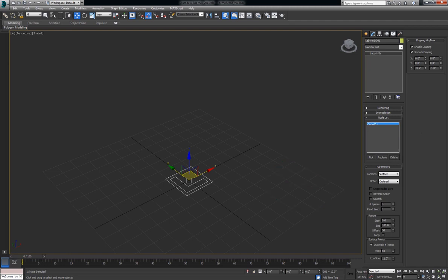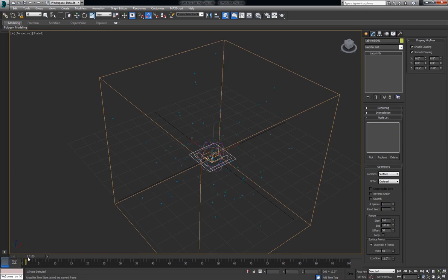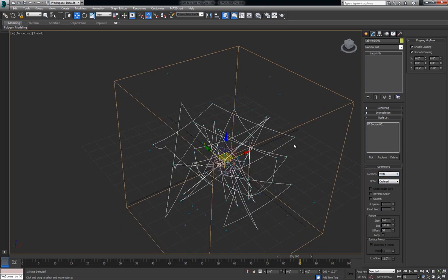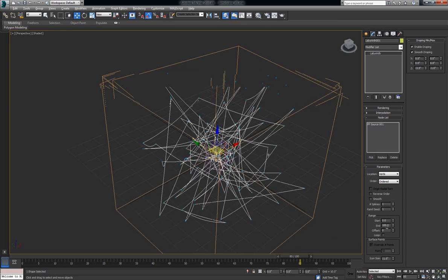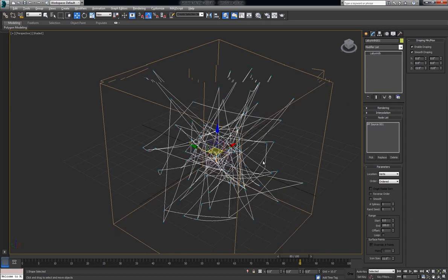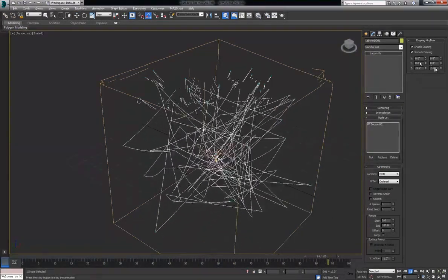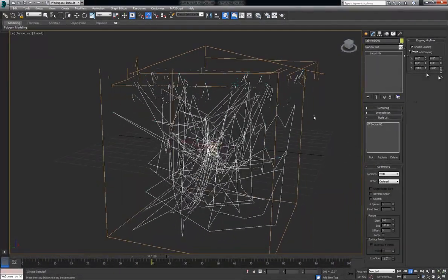Next, I will show you the particle support we have. So if you have a particle system that's generating points over time or all at once, Labyrinth will support that as well. And we'll pick verts, which is equivalent to the points generated in a P-Flow setup. And you can also use offset here. And you'll see as the points move in P-Flow, the spline gets generated. And you can still use the draping effects here. Those still work, or you can turn it off.